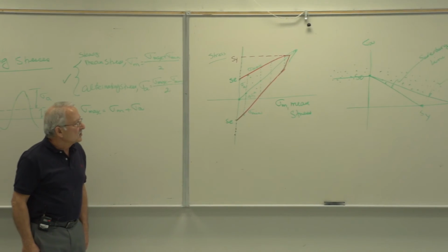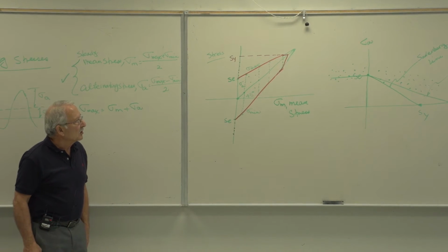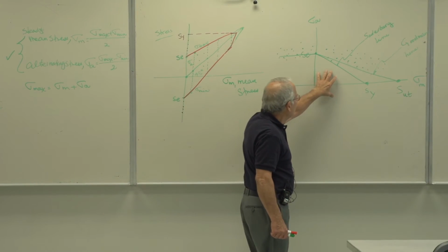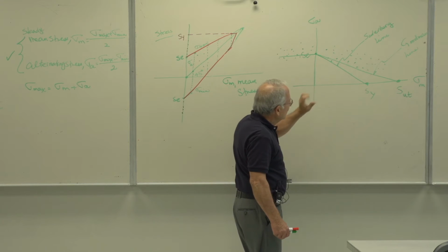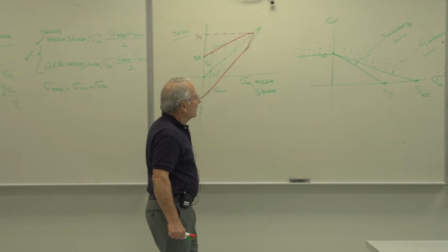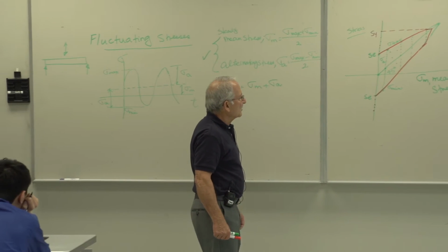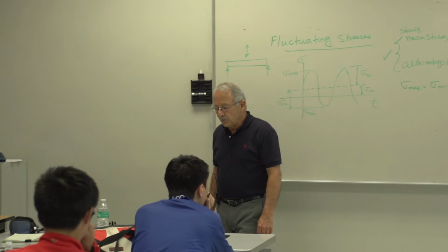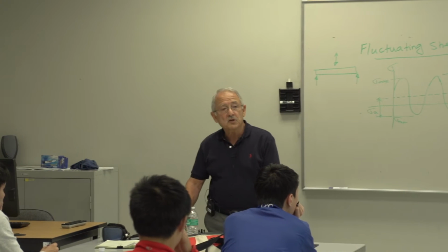This sort of makes sense because fatigue is a tensile phenomenon. Compressive stresses don't propagate cracks. Tensile stresses do. Therefore, that makes sense, and of course, experiments bear that out as well. So your line here would be something like that. That defines failure under fluctuating load. By failure, I mean not having a life of 10 to the 6. Then I'll show you how to use these with the load lines and all of that in just a minute. We also said, any questions before I continue?